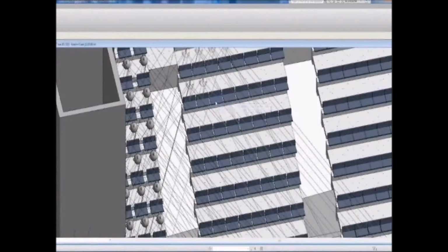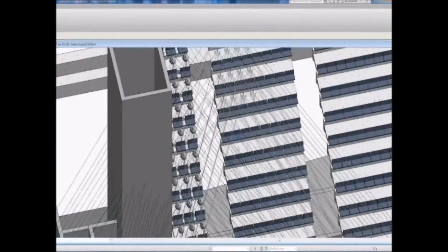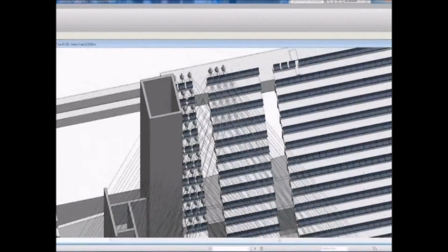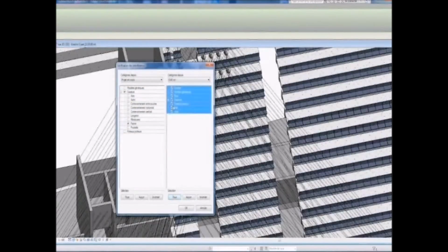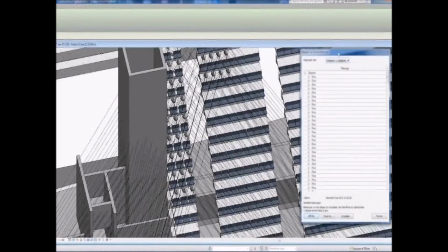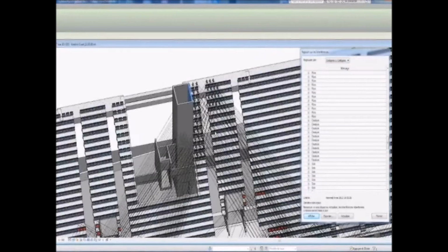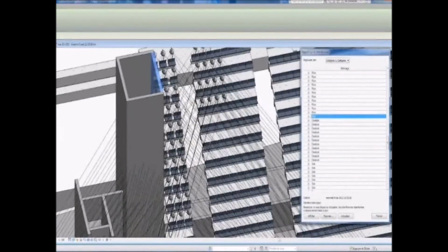The operator figures out the best position for every viewer, and the system draws 4 lines from there to every corner of the stadium to make sure nothing interferes with their vision, in particular one of the supporting pillars for the roof. The computer checks every single visibility line and verifies nothing interferes with it. If anything blocks the visibility line, it will light up in blue. This allows us to know which seats exactly have existing elements interfering with their visibility line.